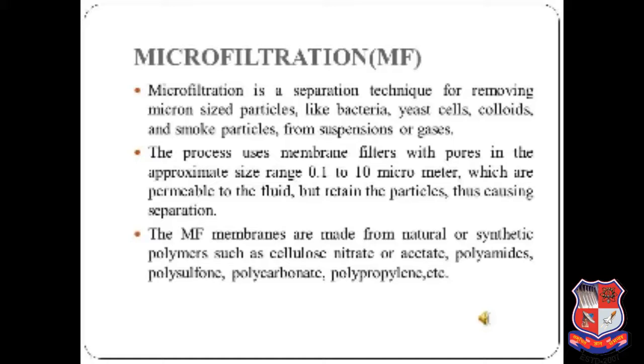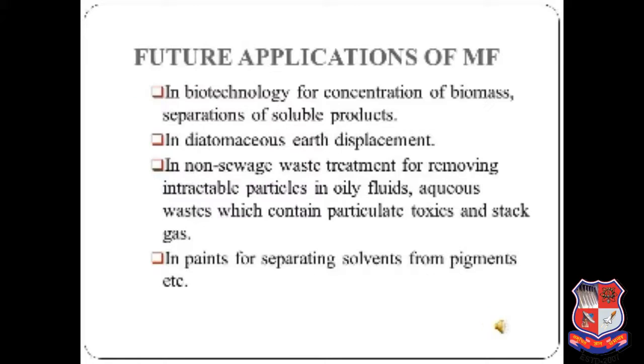Microfiltration systems are designed to remove suspended solids down to 0.1 micrometer in size in a feed solution with up to 2 to 3% concentration. It is very suitable for use in place of a traditional clarifier or as a pre-filter to a water recycling or recovering reverse osmosis system.